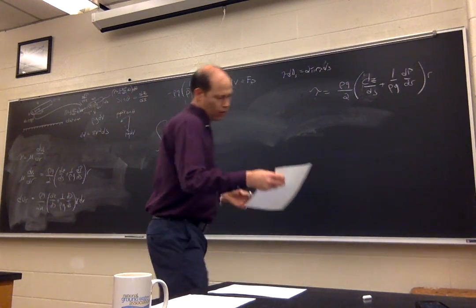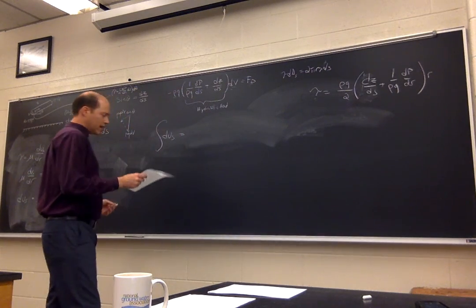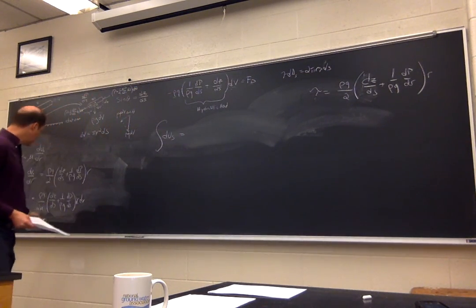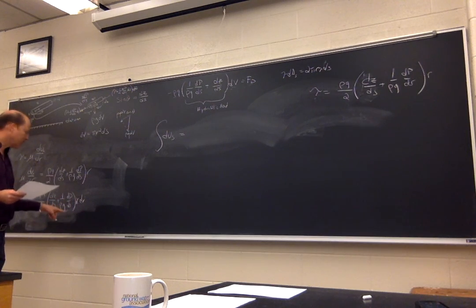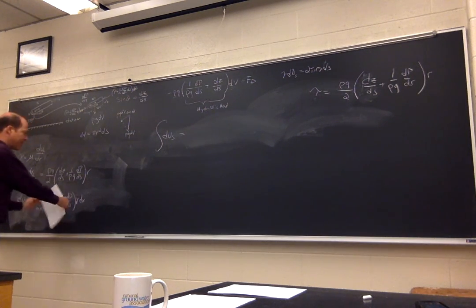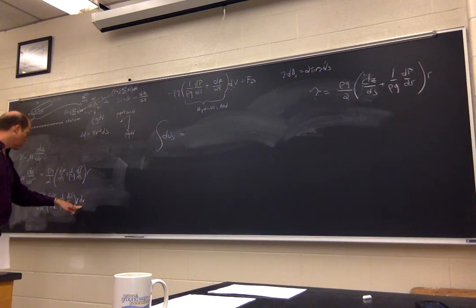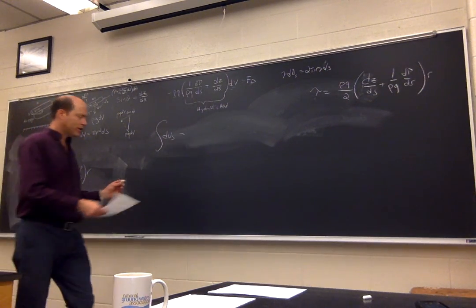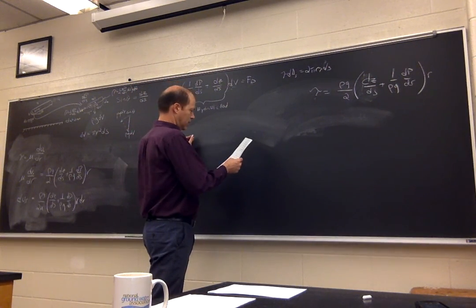And on the right-hand side, I'm integrating up everything else. But notice, going back to this, the density is constant, gravity is constant, viscosity is constant. This part in the middle here has nothing to do with radius, so it is effectively a constant when we're talking about radius. So the only thing that's not constant is r dr in this particular integration.